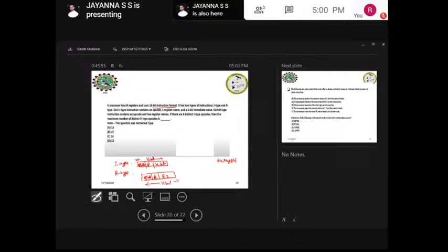First you have to determine the number of bits required to represent each register. For that, again you use the same formula. Number of bits is ceil of log 64 with base 2. You will get 6 bits. 6 bits are required to represent every register. Therefore, R is 6 bits and there will be a 4-bit immediate value. Therefore, the remaining opcode is 6 bits for the I type. Similarly, for the R type, R2 is 6 bits and R1 is 6 bits, and the remaining 4 bits are for the opcode for the R type.